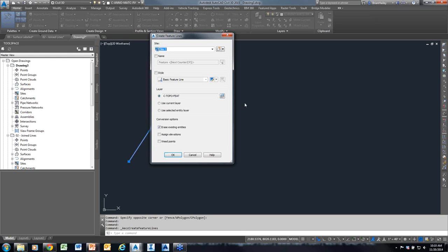Another thing I want you to take away from this is you should never, under any circumstances, ever use Site 1. Why? Well, it's because it's the default site. It's like that drawing on layer 0. You should never, in your drawing, draw on layer 0. Why? Well, because then you don't know what that stuff is. Alright, so in this example, I'm going to use Site 1. Okay, I take that back. The only time you should ever use Site 1 is when you're demonstrating why you should never use Site 1. Alright, so I'm going to put it in Site 1.